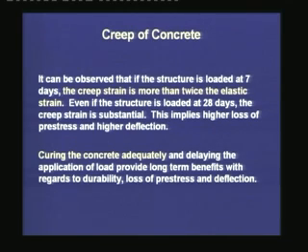Thus, it can be observed that if the structure is loaded at 7 days, the creep strain is more than twice the elastic strain. Even if the structure is loaded at 28 days, the creep strain is substantial. This implies higher loss of prestress and higher deflection. Now, what is the remedy to reduce the creep? Curing the concrete adequately and delaying the application of load provide long-term benefits with regards to durability, loss of prestress and deflection.